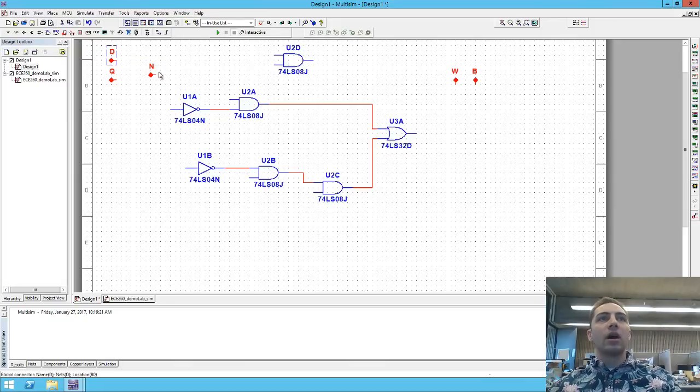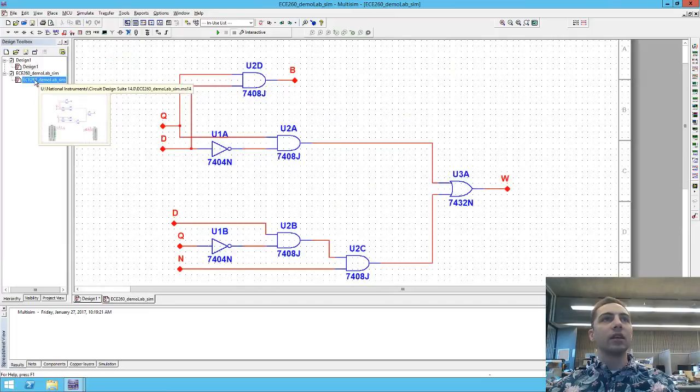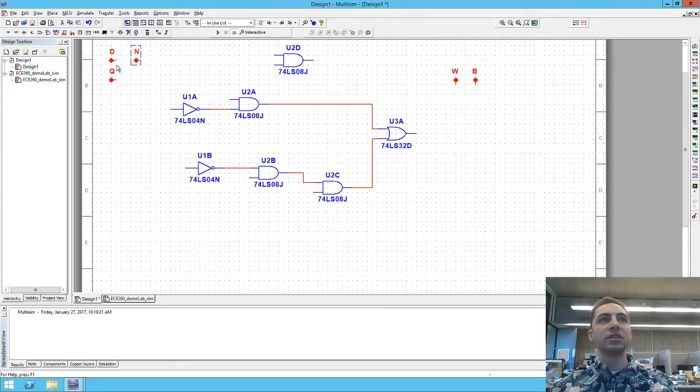All right, from now on, I'm going to just keep these 3 up here and I will copy and paste them when I need individual things. So let's go back here. This AND gate gets Q and D bar, so I'll take that, send him here, copy and paste him. So then I can simply click and connect these, clicking once to start and once to finish. I don't have to use on-page connectors every time. I do have the option to connect to pre-existing wires. Just by clicking on the wire, it automatically creates this junction. But I can do it either way.